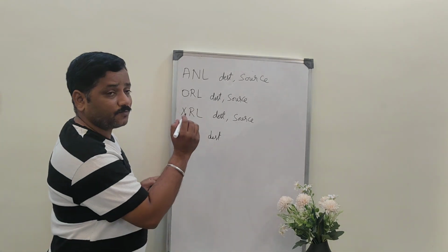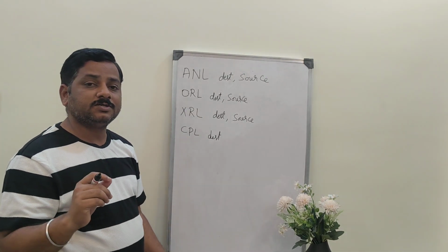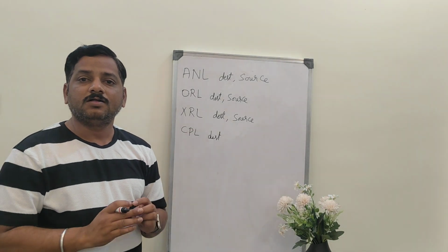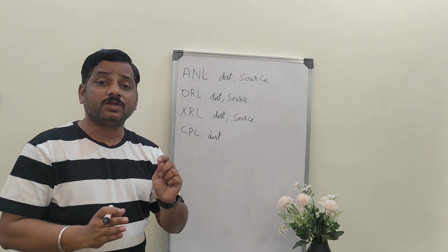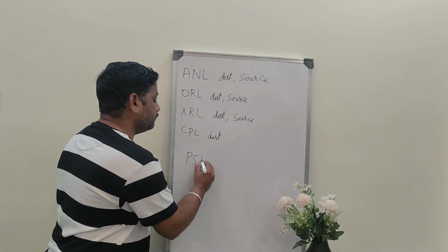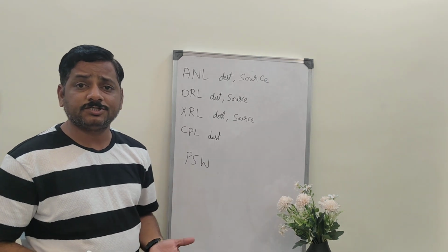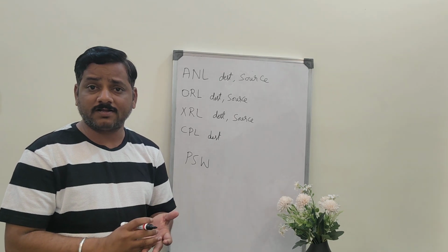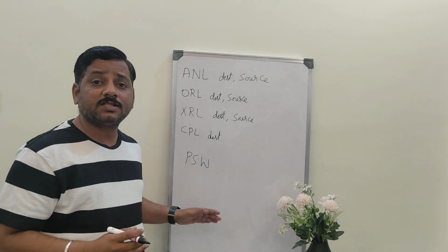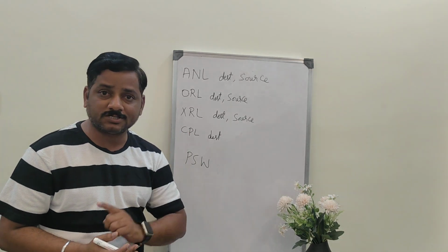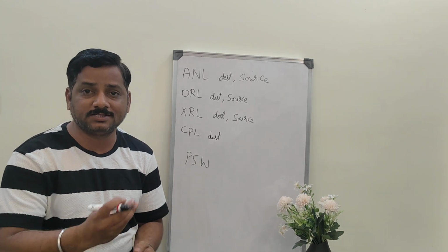One most important thing you need to understand in the logical instructions is that all these logical instructions will not affect any flags in PSW. Whatever flags we have in PSW, like carry flag, auxiliary carry flag, overflow flag, those flags will not be affected using these logical instructions. That is one important statement you need to make when you are explaining the things.